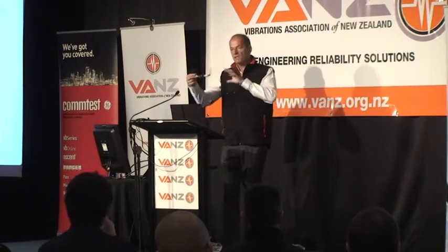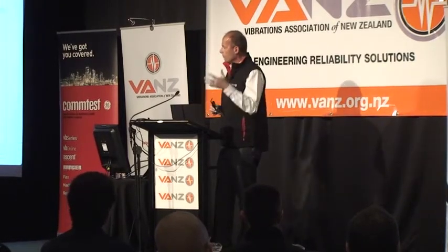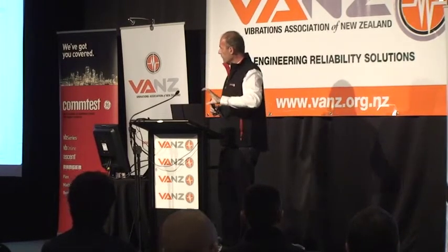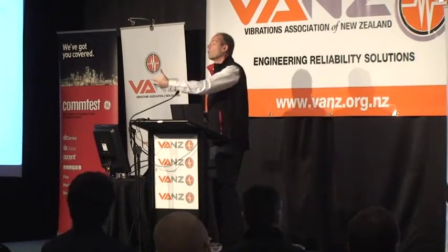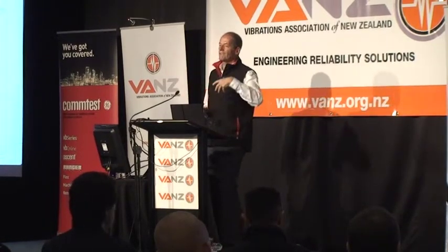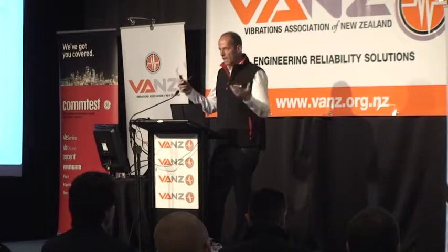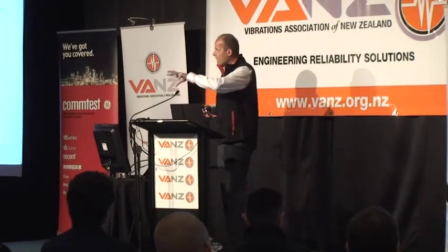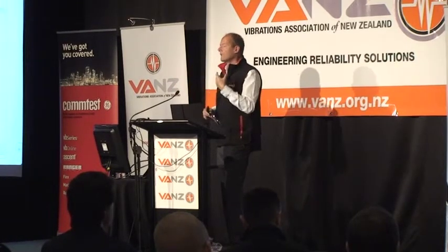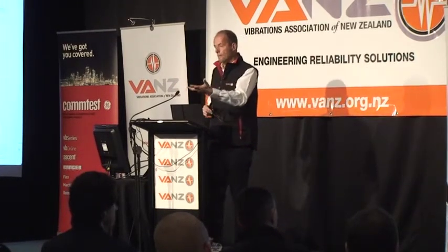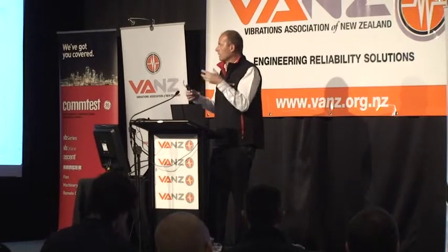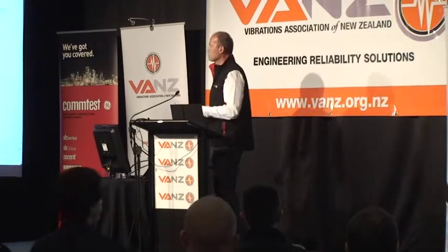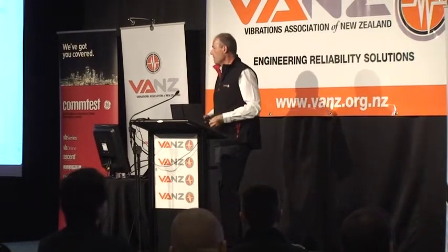Well, yeah, you're seeing something that's hot and something that's cold, but it's important with all of these technologies, particularly with infrared, to understand what you are measuring and understand things like emissivity and other issues, the environmental conditions, how heat transfers from one point to another, and what it actually means if something is hot. What is the root cause? What is it that needs to be repaired or dealt with? And that's the problem.